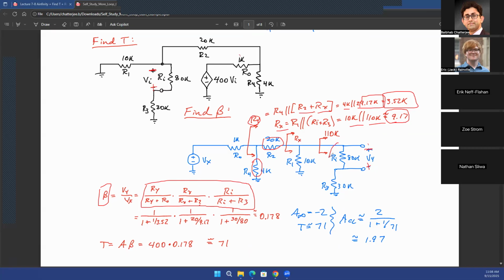Remember, you're interested in the voltage drop across Ri. So whatever contains that voltage drop would be your factor of interest. For example, for the third component, you're interested in Ri divided by Ri plus R3 because you want to know the voltage drop across Ri. And you know from the first lecture that the voltage drop across a resistance is proportional to the value of that resistance. So you're interested in Ri.